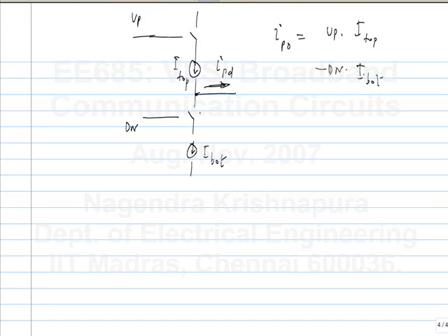That is the current that is flowing out into the loop filter. Okay. So what I have plotted is really this much, just for getting a more intuitive feeling. Of course, up is a logic signal, so it doesn't make sense to talk about amplitude. The state is either 1 or 0. What I have plotted is the state of the up signal times the current that it is passing.